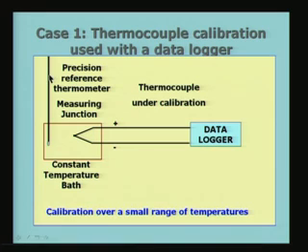So, I will subject the thermocouple which I want to use in my experiment to the same temperature as the precision reference thermometer by putting the two together in close proximity within a constant temperature bath. Okay. So, in principle, whatever temperature is indicated by the precision reference thermometer must correspond to a certain voltage developed by the thermocouple under calibration, and I am using it in a form without the reference temperature being at the ice point.